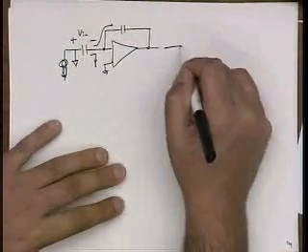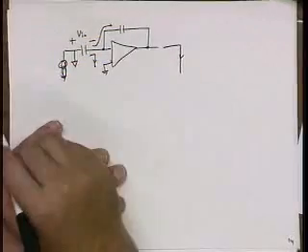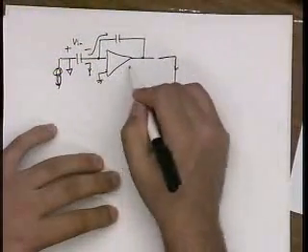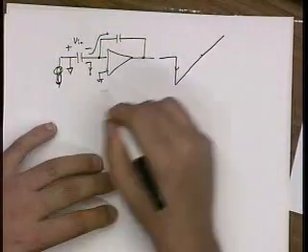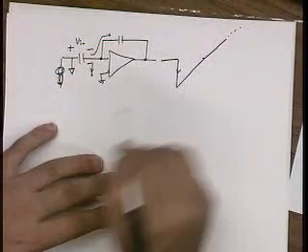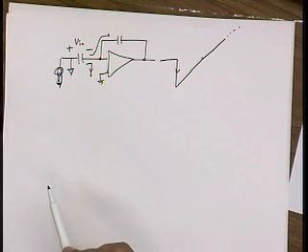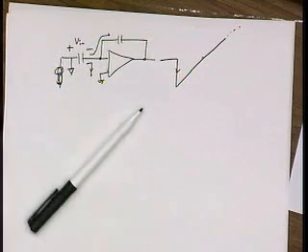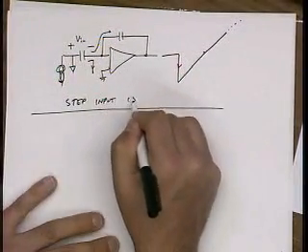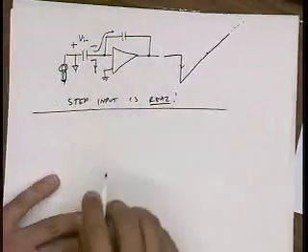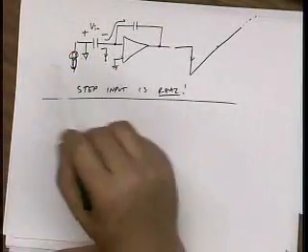And we know that at the output of the amplifier, the step just travels through, so I get a step at the output, and then that causes this ramp to occur, and then finally, of course, we get into this linear settling region. So in fact, this is a very realistic scenario. It happens every cycle in a real amplifier. So the step input is actually real. We really do care about the settling time for not a small, tiny little step, but a big step.